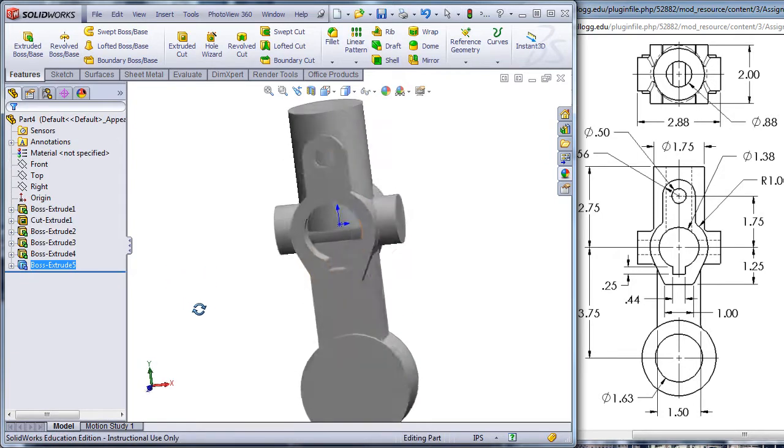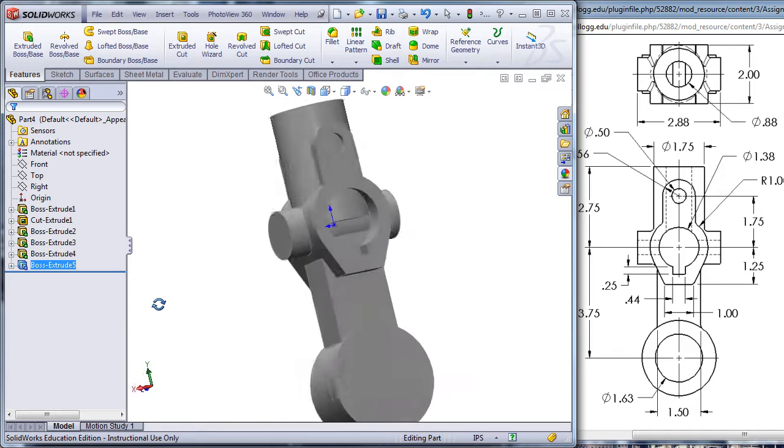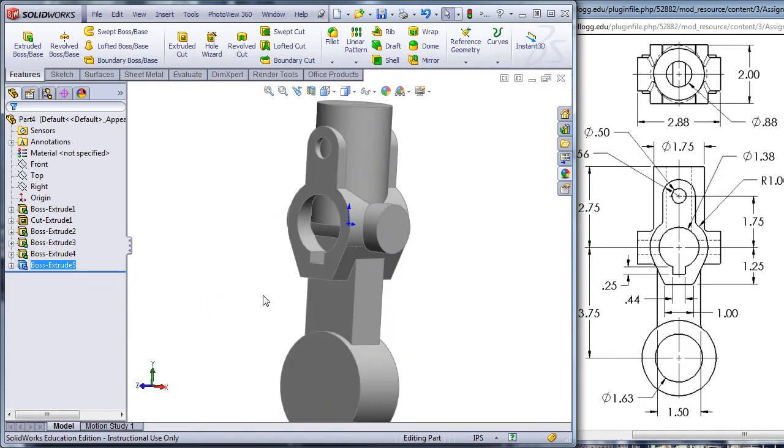Now again, I've now completely plugged up the holes in the middle, right? I can't see through there. And I said, well, we should do all our hole cuts separately, and we should do them last. Let's see now how history works in SolidWorks. This doesn't always work, so this will look really cool, but sometimes it won't happen. The cut extrude was done in time, if you will, as the second step. Well, it really needs to be the last step in this sequence here.